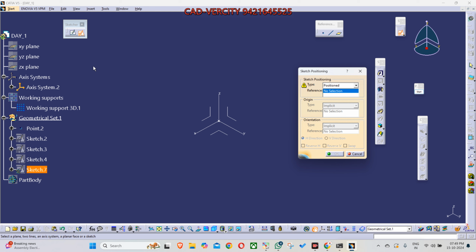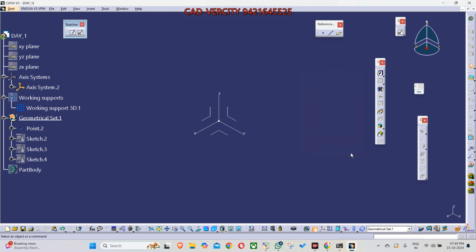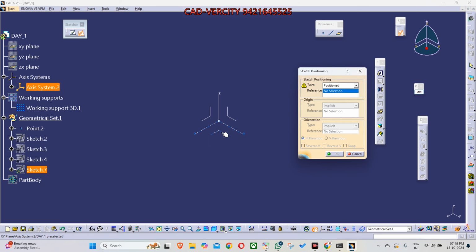We are going to start the sketching workbench now. So we had done the square or rectangle. This is the triangle. This is the circle. Again, hide, hide, hide. Position sketch, top plane. Tell me what should be the orientation? V reverse, H reverse. Okay.